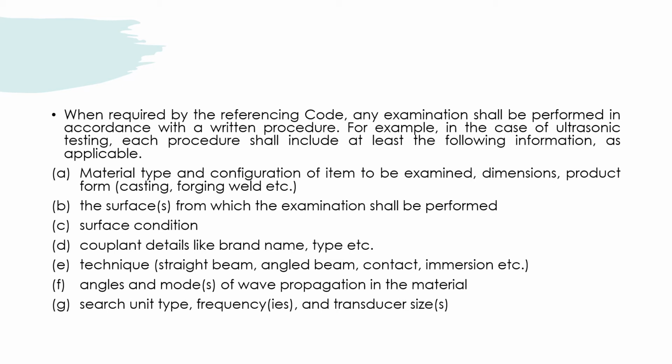Dimensions, product form, that means casting, forging, weld, etc. Number 2 is the surfaces from which the examination shall be performed. Number 3 is surface condition.